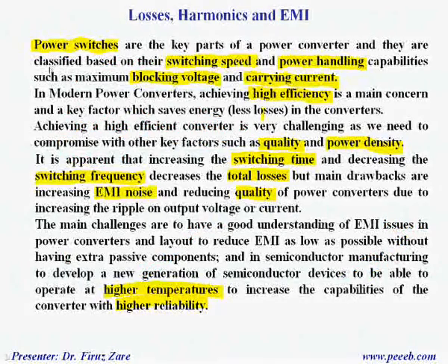Power switches are the key parts of a power converter, and they are classified based on the switching speed and power handling capabilities, such as maximum blocking voltage and carrying current. In modern power converters, achieving high efficiency is a main concern and a key factor which saves energy in the converter.